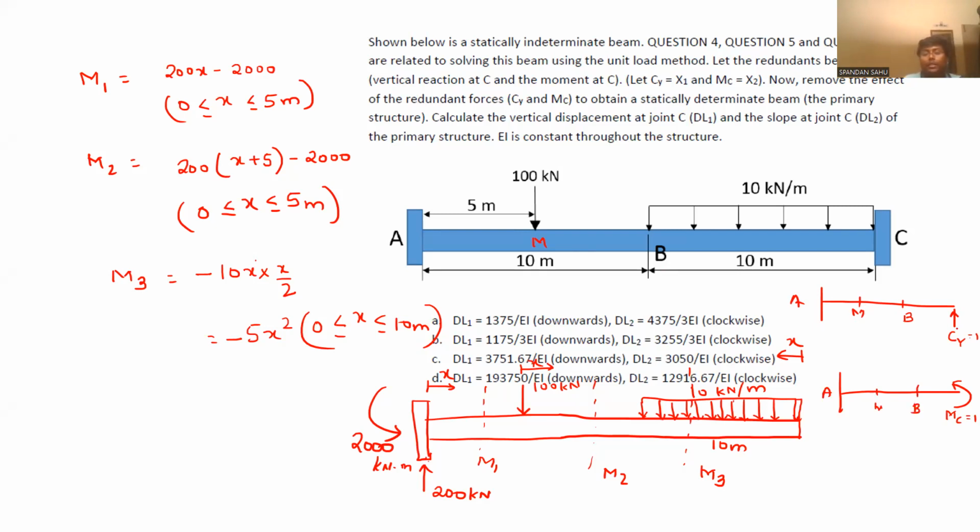Now you tell me, this one unit is acting upward, so one unit will act downward. This one and one will try to rotate it anti-clockwise, so a clockwise movement should come, and the clockwise movement should be 1 into 20 kilonewton meter. This M will be balanced by 1 M only, and the structure is balanced without any reaction. There won't be any reaction.